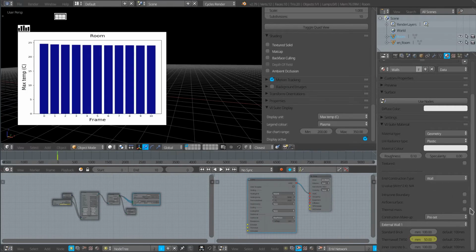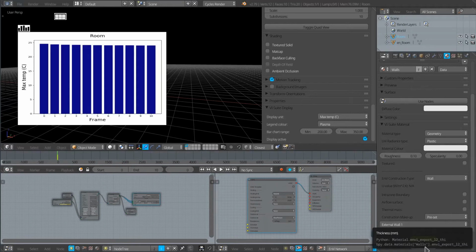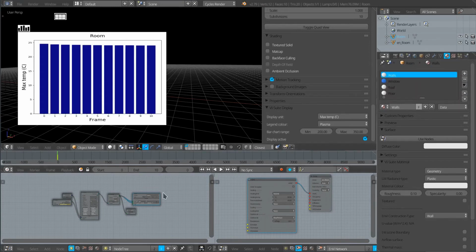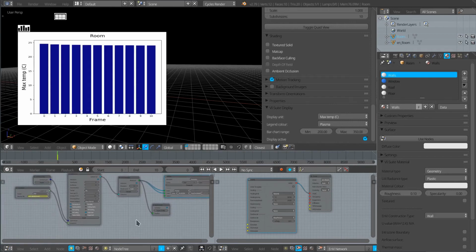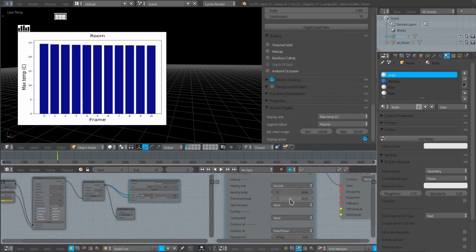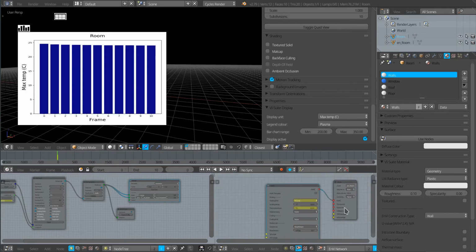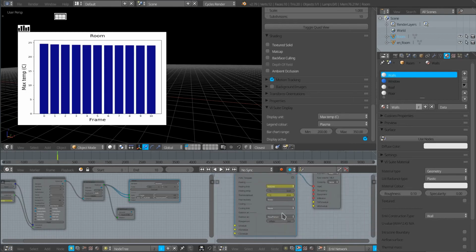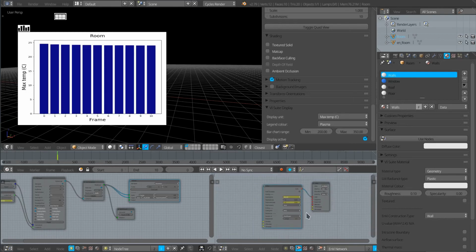But certainly in terms of the parameters around thickness of your walls, the geometry, material specifications, that can all be keyframed in Blender. We could come in here and we could change the thermostat level. We could change what kind of heating system it's got. And that applies to zone, occupancy, equipment, infiltration, all the sort of EnVi network nodes as well. So there's a lot of potential for setting up the parameterization of individual or groups of variables within the simulation.